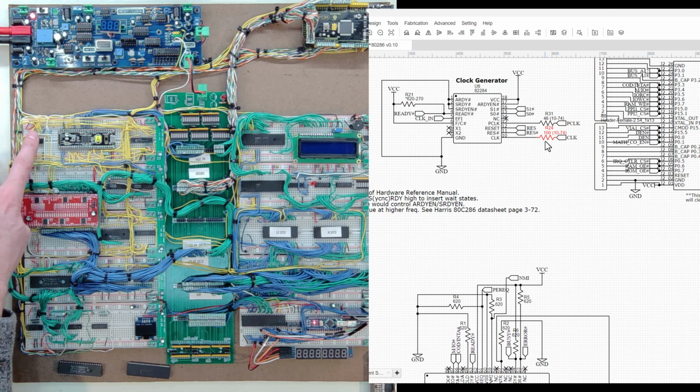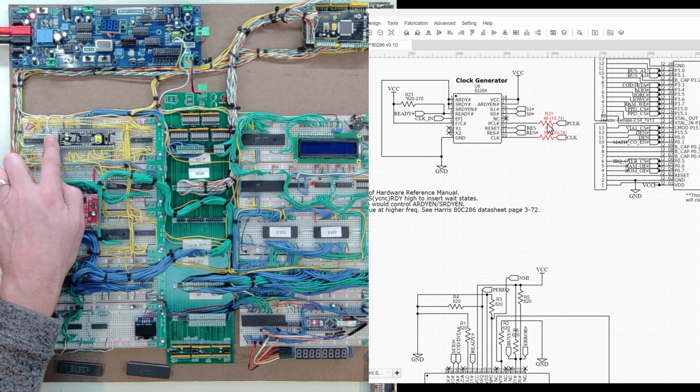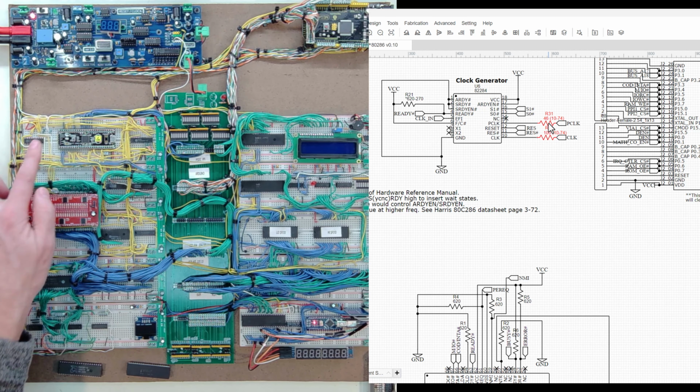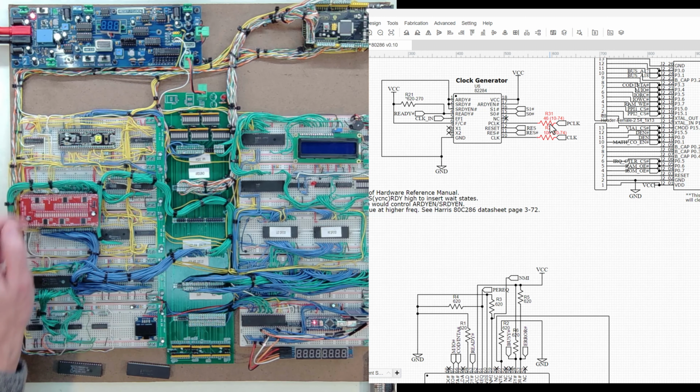So I've gone from a 10 ohm resistor right here out of pin 10, and I changed that to a 100 ohm resistor, and now everything is happy. I've left the P clock resistor at 46. So I'm using a 100 and I'm using a 46. I did try 100 where the 46 is on P clock, and that caused different issues, so I put that back to 46. I put this one at 100, and all the testing I've done so far is looking good.